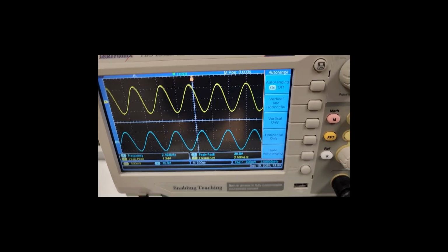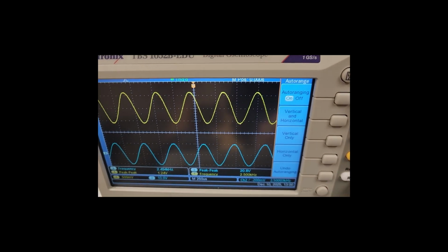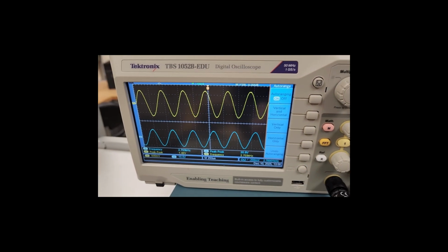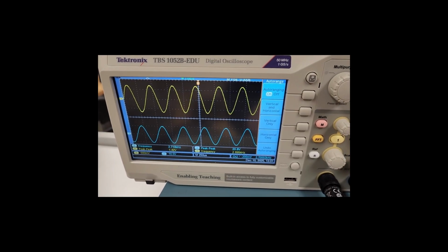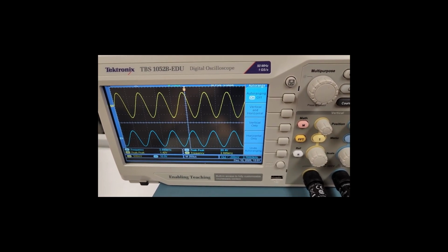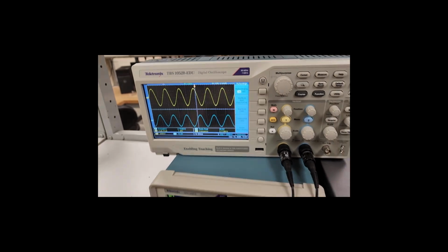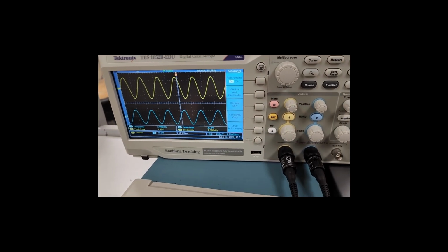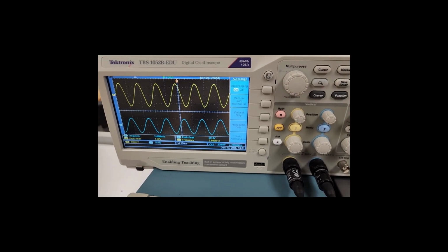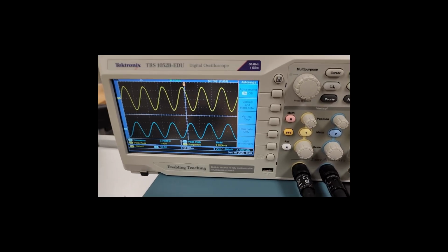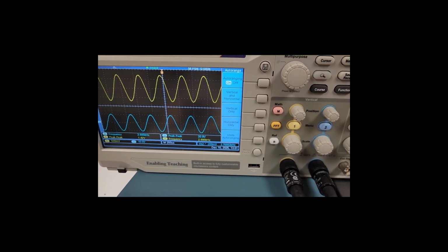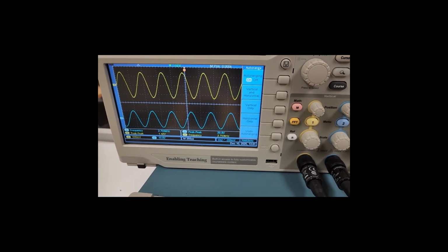Now there are some other things that you may be able to notice. It took me a while to analyze all this stuff, and I did a lot of reading and research on it also. I realized that when you're doing this, you also need to research the op amps that you're working with. What I learned about the 741 was that there's a slight phase shift as you move in frequency.